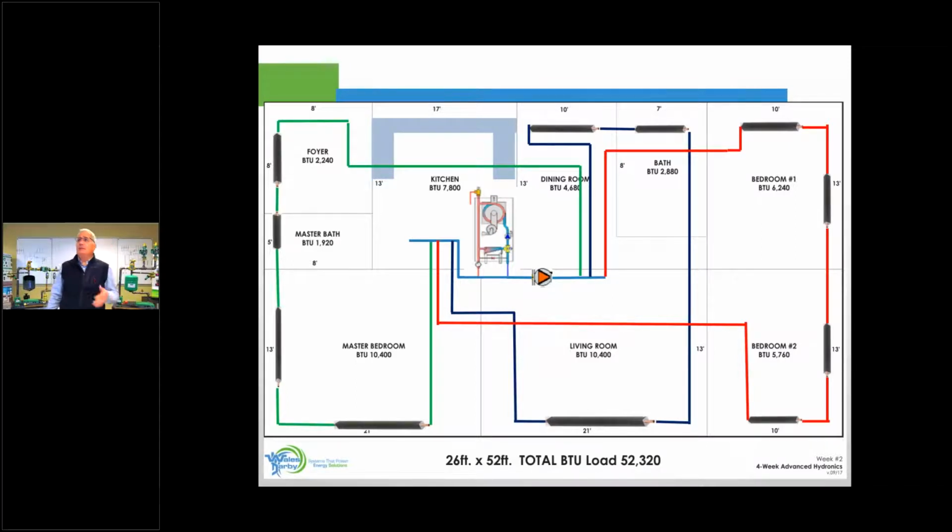So if you take a look, we did give you the lengths of the walls. So if you want to do your best guesstimation, but I came up with about 84 feet. So write that number down. So I know I have to move 1.2 GPM for that zone, and I have to overcome 84 feet of piping resistance. We're going to do the same thing per zone. So before we leave the red zone, I have to figure out the head loss at 84 feet.